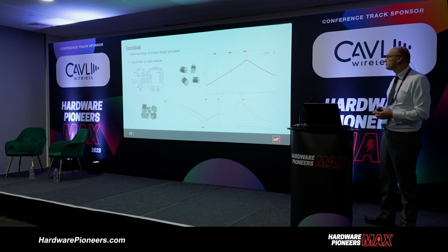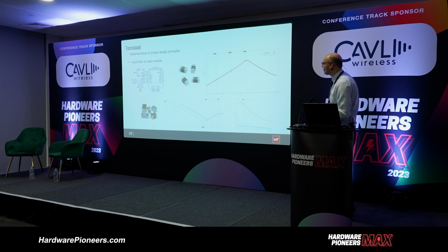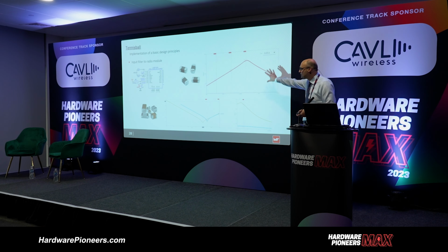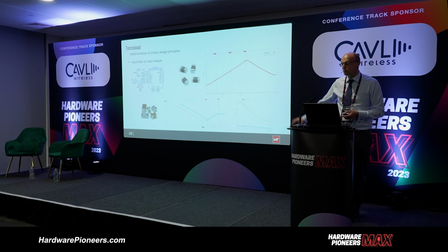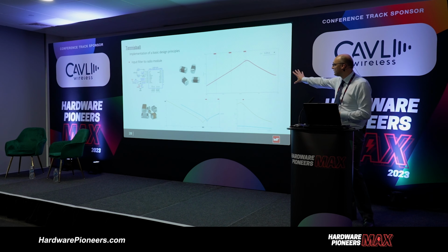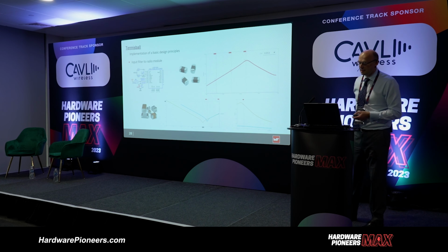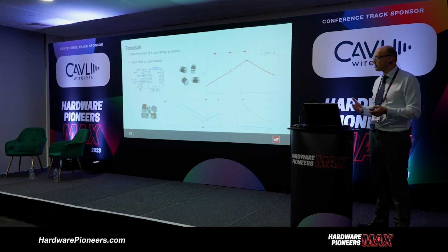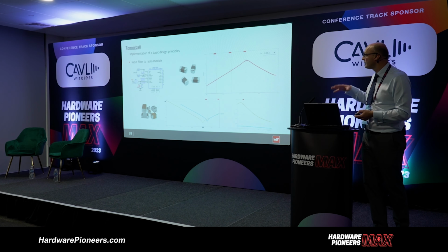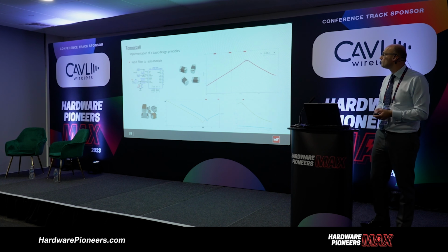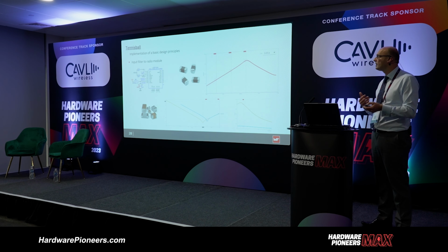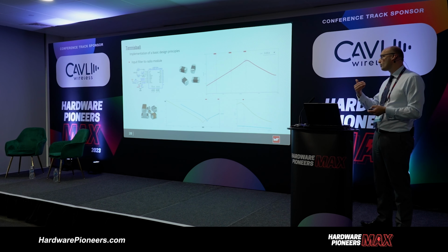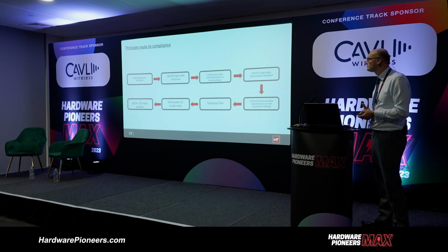By doing that, we use an online tool called REDEXPERT for designing in the capacitors, looking at actual capacitance values, and looking at the inductors to make sure we have the correct amount of suppression. We're typically aiming for 40 dB per decade to make sure that we can keep the module compliant, and make sure no noise is able to get into the module, or once again, noise to get back out.